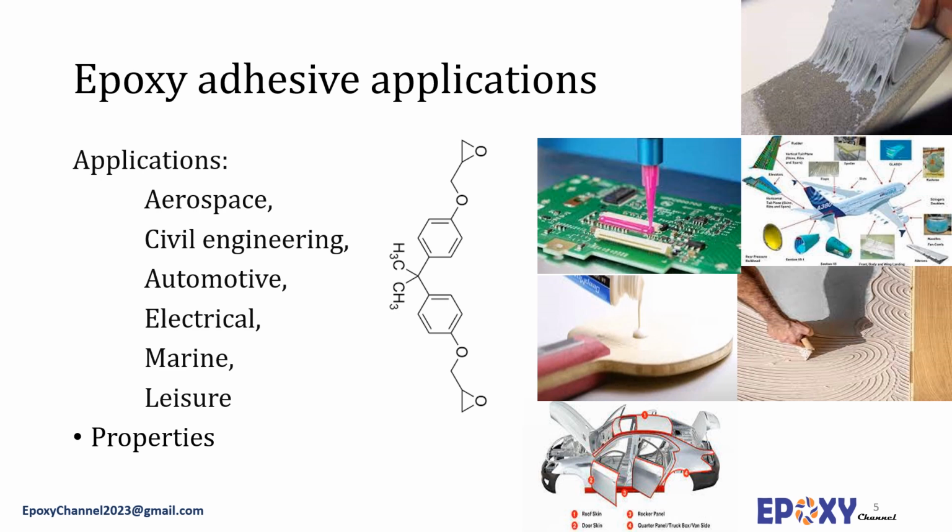Because of the various types of epoxy resins, hardeners, additives, etc., a vast number of epoxy adhesive formulations exist. However, the most common epoxy type used in the formulation of these adhesives is the conventional diglycidyl ether of bisphenol A resins. A large number of curing agents can be employed in this system. Other components often found in the adhesive formulations include accelerators, catalysts, viscosity modifiers, fillers, and additives such as toughening agents, wetting agents, etc.